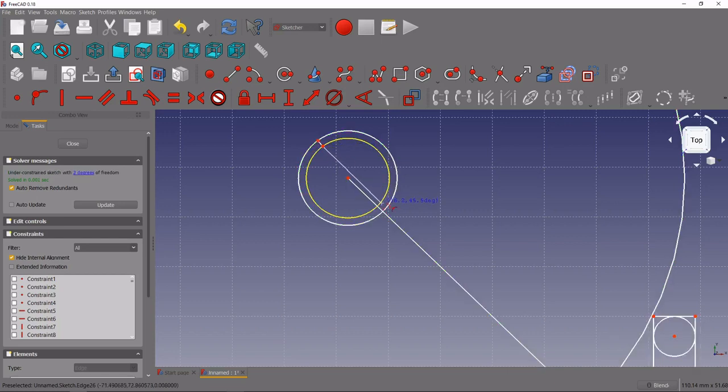It doesn't have to be perfectly collinear. Now that we've drawn those, we'll select all three lines and we will add a parallel constraint right here. And then we will fix this line onto the center point of our circles by using the fix onto point constraint. And now we've got a line here that can rotate. If you select one of these outer points, we can rotate it.